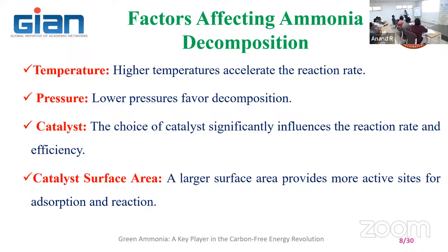Lower pressure favors the decomposition, because when you go for higher pressure, you may need some residence time to adsorb the ammonia over it. It will be immediate, right? And the ammonia will come out from the reactor very quickly.